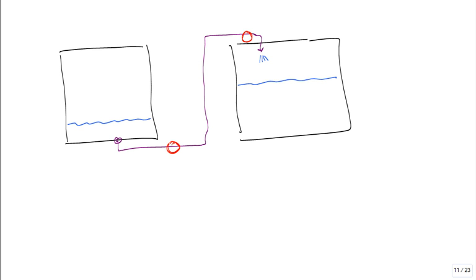Always put the pumps low, because if you put the pump on the top of the second tank, it's got to draw that water up. And even if the pump's not running, what is the pressure in the pipe right there? It's the gas pressure in the tank, typically atmospheric pressure. And if you try to run this pump, it'll try and draw that water up by sucking it. And that pump will have a very hard time of actually getting it to go anyway. And if you did get it to go, it'd be very susceptible to cavitation.